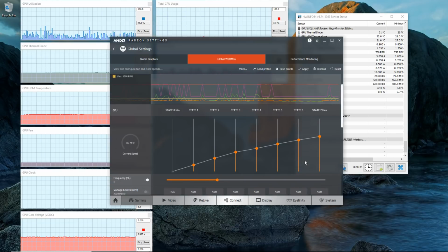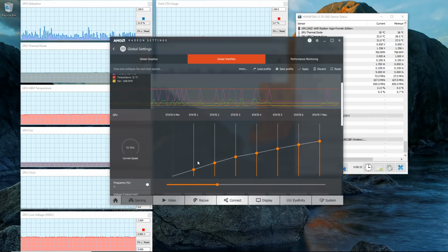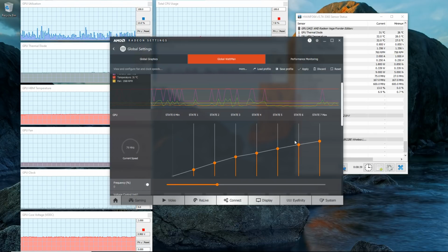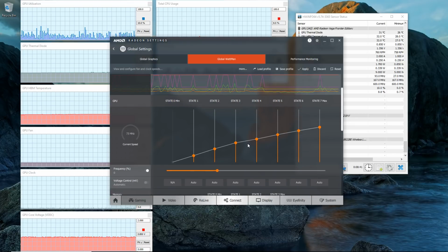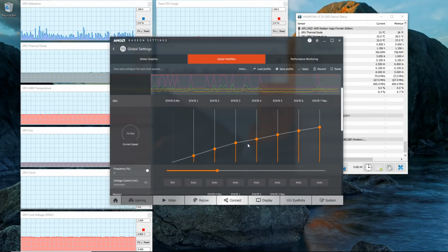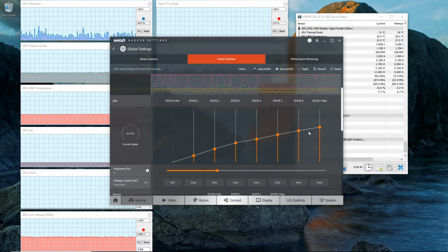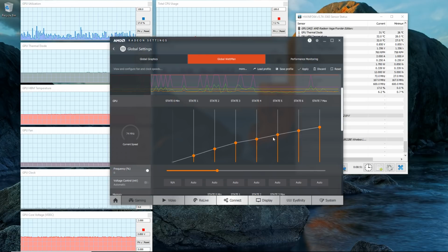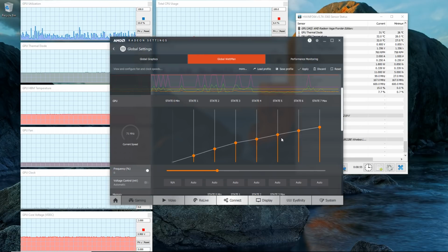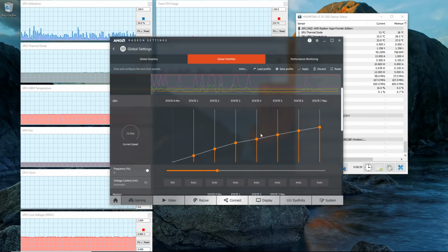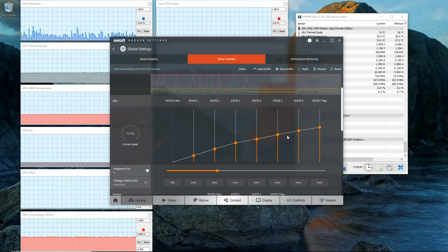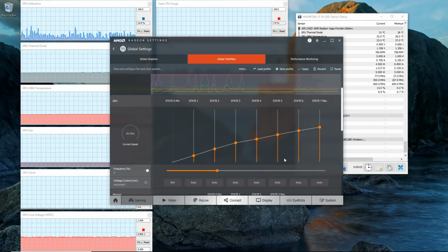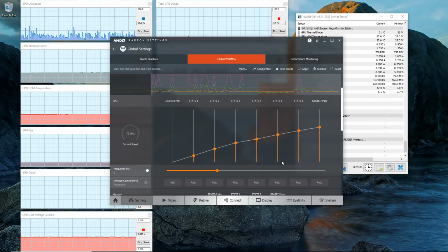On the Frontier Edition, we can modify all of the states here. So all of these power states that exist can be modified. I don't know if that's the case for the Vega 56s and the 64s. I knew at one time it was just state 6 and state 7 that can be modified. If that has changed recently, then that will make this process a little bit more flexible. Otherwise, if you've got a Frontier Edition, you have access to all of these, you can follow this tutorial exactly. Otherwise, you're going to just have to skip the state 5 work that I'm doing here and just move right to state 6 and state 7.